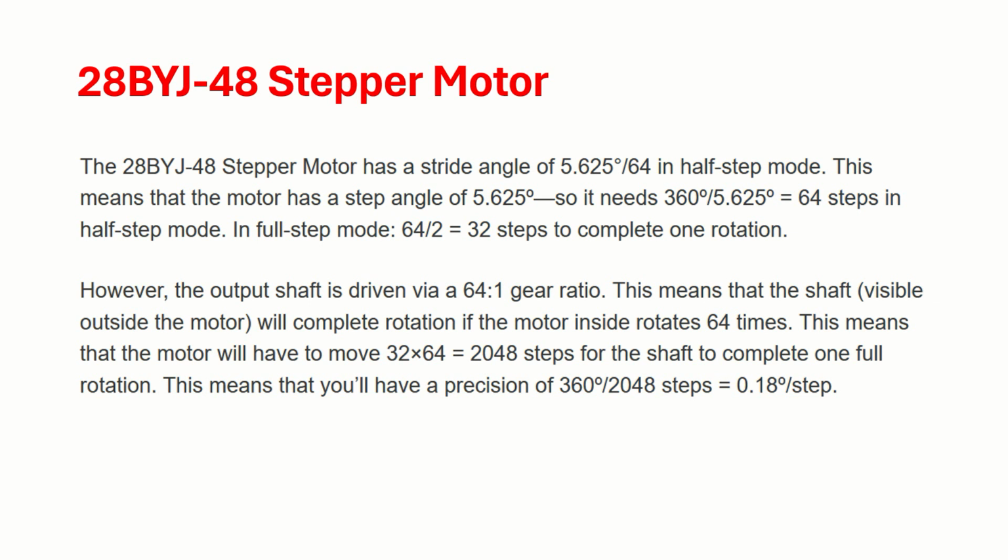All right, so these are at least the basic motors which are used in robotic applications. What we have seen is a DC motor, which is good, control is good, direction is good. However, there is no feedback. In case of a servo motor, it has inbuilt feedback. It's really good for displacement because you are controlling the pulse width. So from an accuracy point of view, it's good. Third, you have a stepper motor, but it's not for heavy loads.